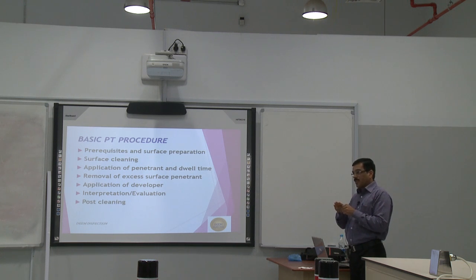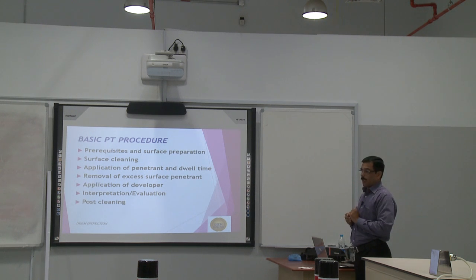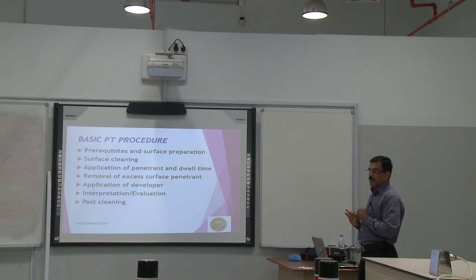So like power brushing, maybe the powder from the power brushing may enter into that small crack opening, and it will close. So maybe it's very difficult to get in the penetrant test. So whenever we are doing the surface preparation, some methods like sand blasting and power brushing are prohibited and they are not allowed to do the surface preparation.